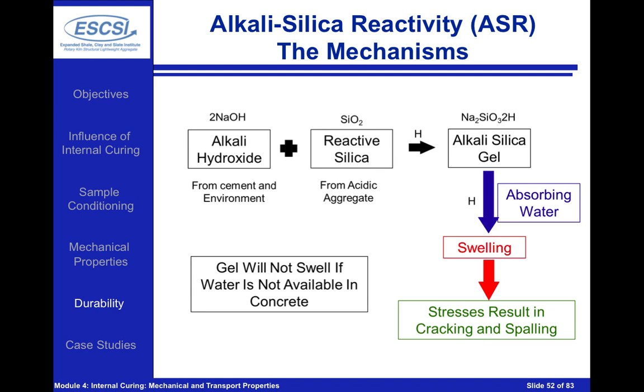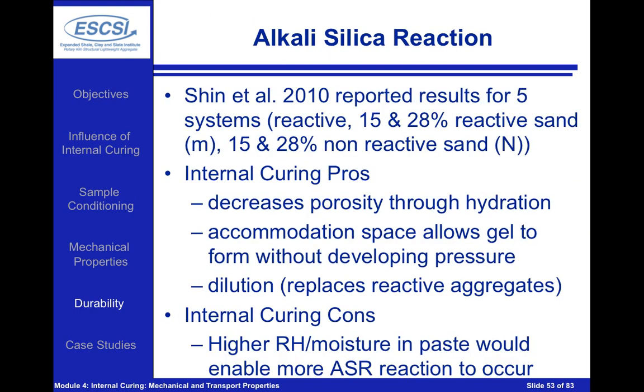In addition, people have examined alkali-silica reaction with internally cured concrete. The whole idea here is that the alkalis will come from the cement and the environment. They'll react with the amorphous silica that can be in certain aggregates. That reaction will form a gel. That gel will take on water, which will swell, and if it's sufficient, can cause cracking. The question was, can internally cured concrete help with this?